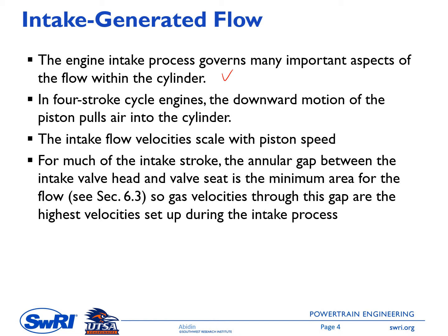The gas velocities through this gap are the highest velocities set up during the intake process. We looked at the possibility of choking when the engine speed is at a certain level. If you'd like to review it again, it is in chapter 6.